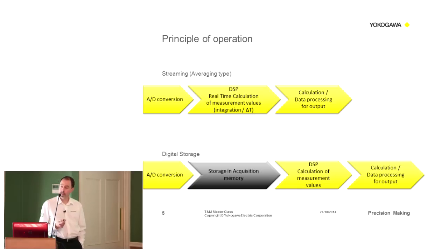So essentially, that's the drawback of using an oscilloscope type product, a waveform analysis type product, for measuring power, because there are bits you miss. If you are looking to integrate power and look at your watt hours, you won't be measuring all the watt hours because there are dead times associated with it.